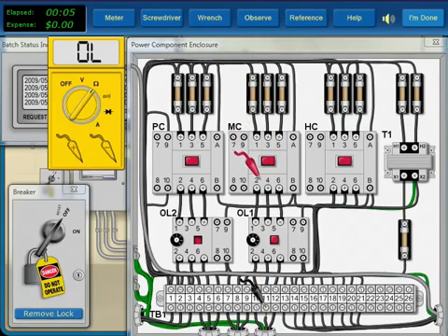We split this area in two at the bottom of the contactor. The low resistance reading tells us the open is above the test point. Testing at the top of the contactor with it closed indicates the contact is okay. Now, the only possible causes are one wire and its connections.